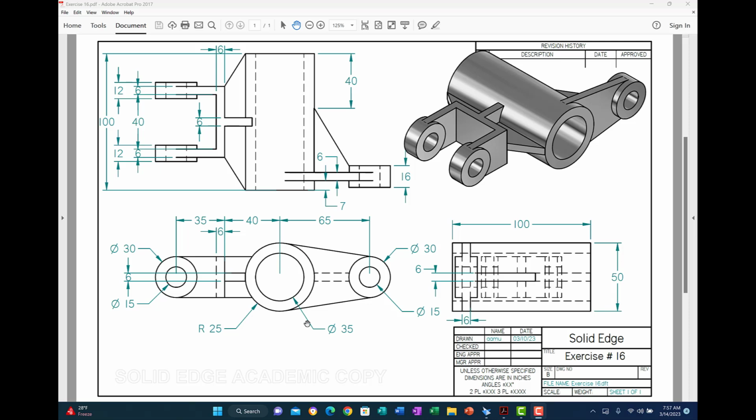The diameters are 50 and 35, and then we're going to use the symmetry here and build a new plane that is parallel to the front plane, but at a distance from the center. I'm going to put my current axis at the center here. As a distance, they have 7 here and 6. I need a symmetric extrusion, so half of that 6 is 3. So 3 plus 7 is 10. So the new plane will be either 10 from the edge or 40 millimeters from the center.